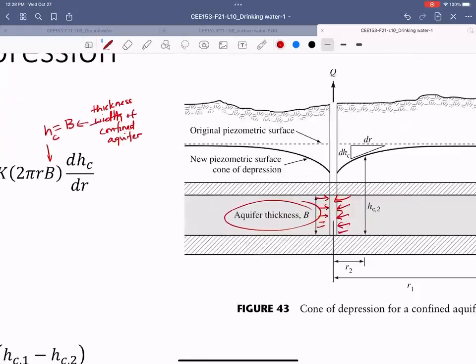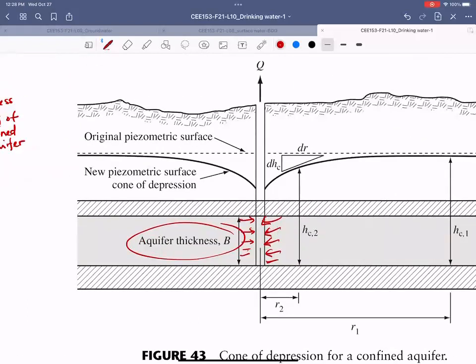And this head over here is not necessarily inside the unconfined aquifer. This is just an imaginary head. If you just draw a well there, how far the water will rise there. So this just looks like it's drawn on unconfined, but it's not. Just imagine you dig a hole here, and you'll see the water depth over here. That's because upstream, that's the head pressure over there.